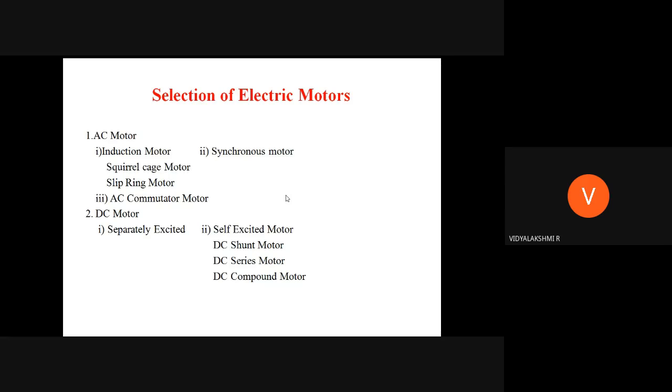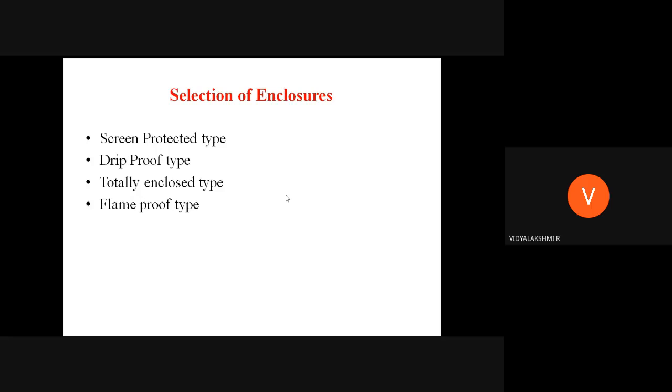Yes. The next topic is selection of enclosure. The electrical motor used in the drive is enclosed with a cover to protect it from dust. The motor is enclosed because in some cases we need to prevent human contact or dust, or in some explosive atmosphere we cover the motor with some enclosure.